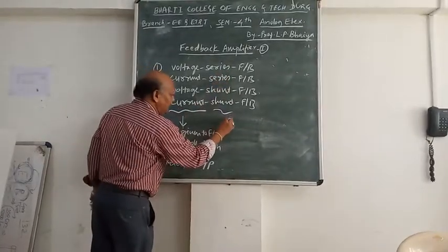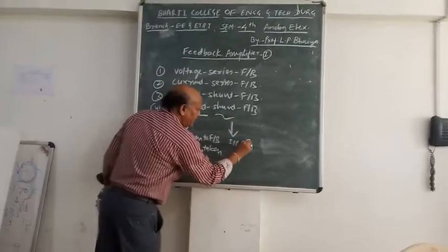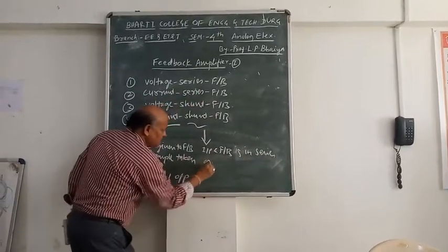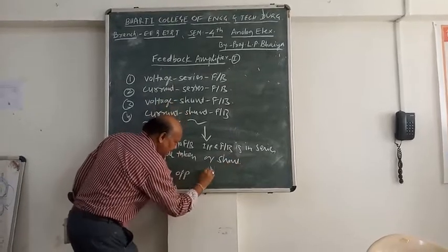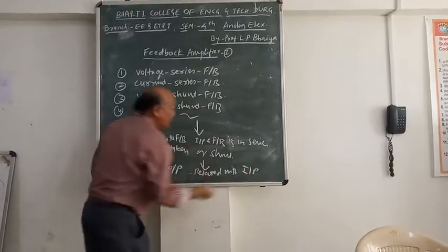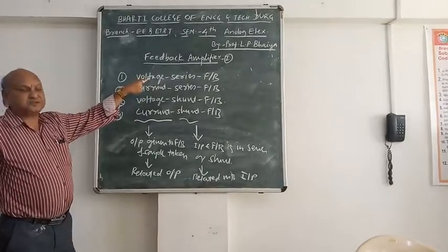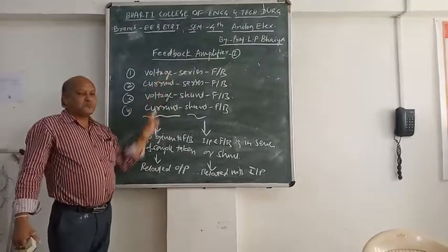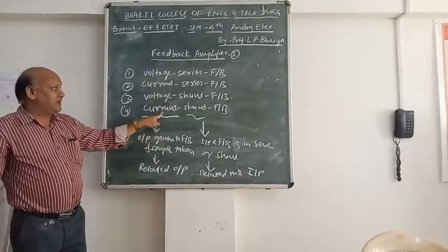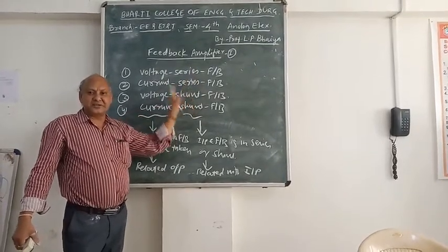And this is the input related, whether the input and feedback are in series or in shunt. So dear friends, remember, to form the topologies of the feedback amplifier, there is the sampling of the output, either voltage or current sampling, and the connection at the input, either a series connection or a parallel connection, that is shunt.